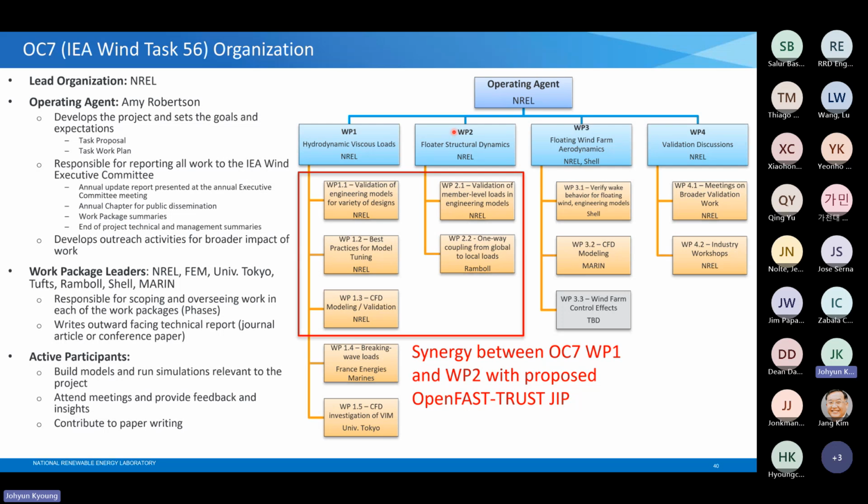We don't need to iterate, but I agree. I think we should. But we have recently had some projects for very huge 20 megawatt turbines with the floater, then you need to consider both the floater fully flexible and include the added mass for the deformation mode shapes and the tower flexible. But that's a different story. Then you have structural dynamics. That's what we can do.